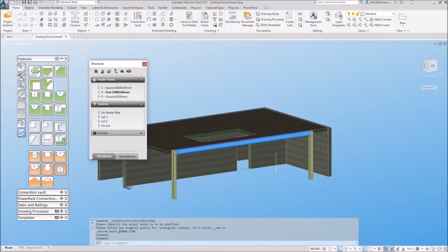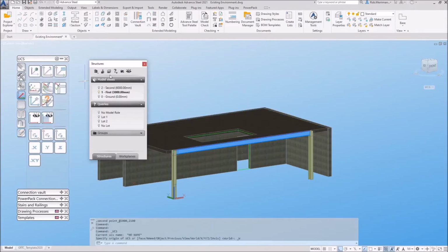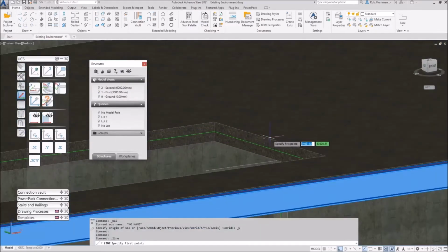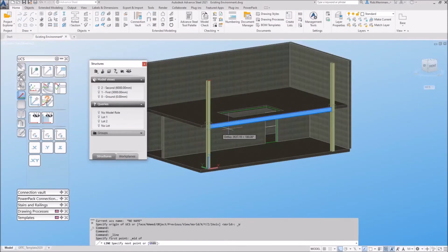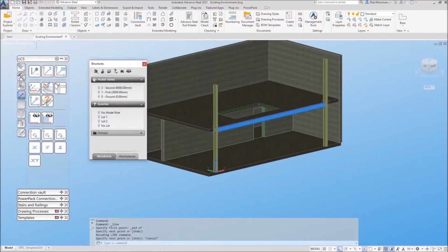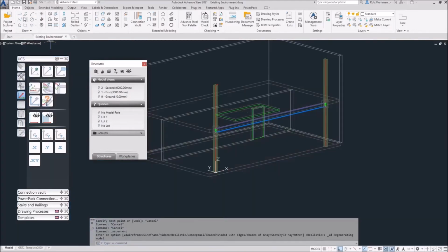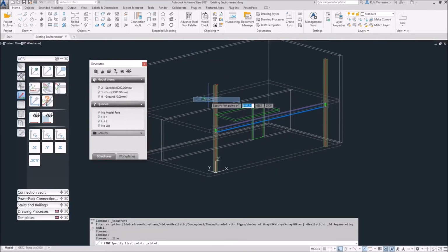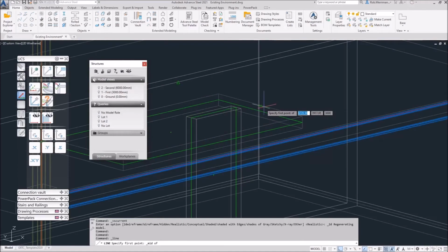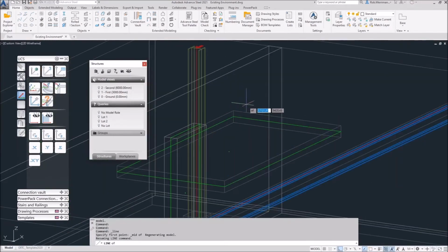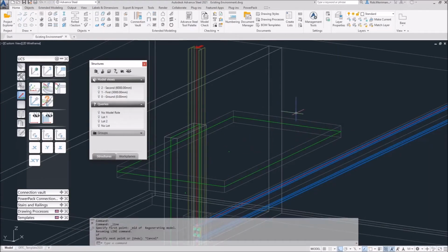What we're going to do, we're just going to model in a quick staircase. Just set that to world and deactivate the level. I then want a line, I didn't quite find it, we'll go to a wireframe. I want a line from the midpoint like that.